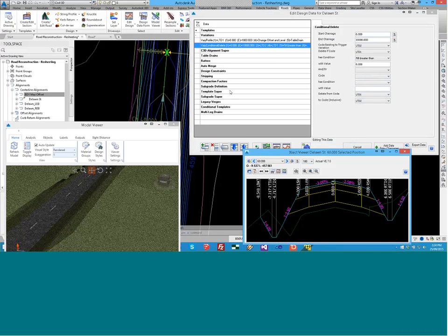So I suppose as I was getting at, the benefit of this is this table drain is actually controlled on a string, controlling the levels, but I'm able to set a condition at which the table drain is inserted based on a code being in cut or fill. So just wanted to show you that one. Only came to mind recently because someone had mentioned it in tech support. So let me just, we can leave that one up.